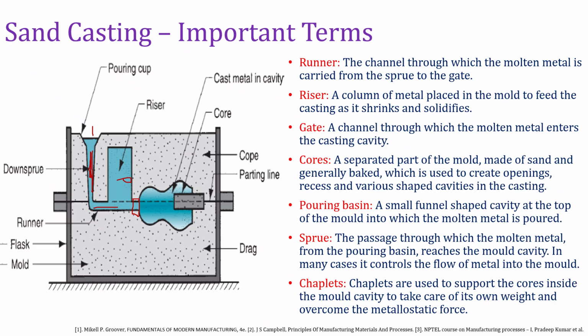So a molten metal cools, right? Whenever the molten metal goes from liquid to solid, there will be some shrinkage. To compensate for this shrinkage, the riser acts as a reservoir of liquid metal.